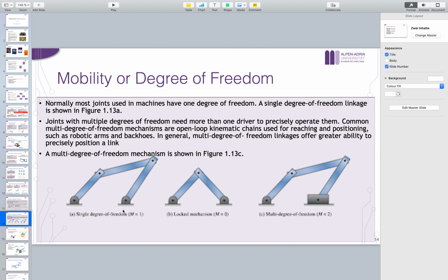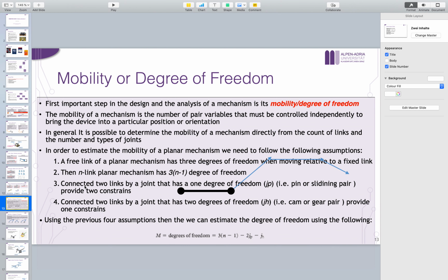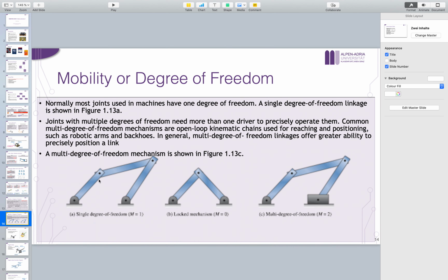So just here for information, as I said, there is always a frame. So if it is at least 2, that doesn't mean we have 2 links. Here we have 1 link, because we have 1 base always. Base is base. So wherever it is located in the mechanism, it is represented by 1 frame. Now we have here 1 frame. We have 2, 3, 4 links in general, so let's say it is the same case as the example that I gave here. So we have 4 links in general, like this one, and we have actually only 1.